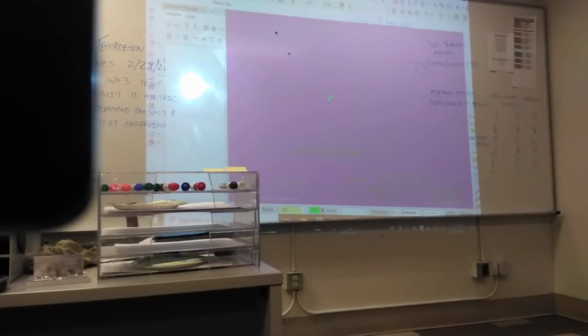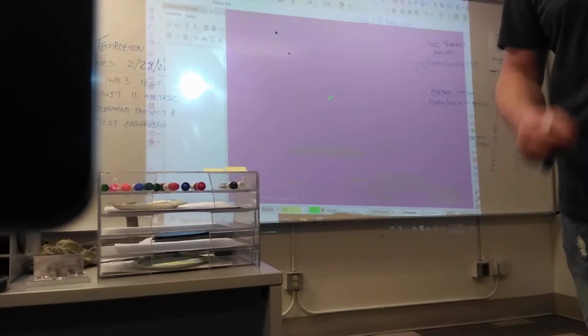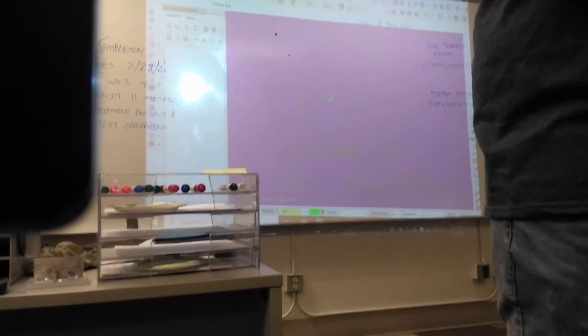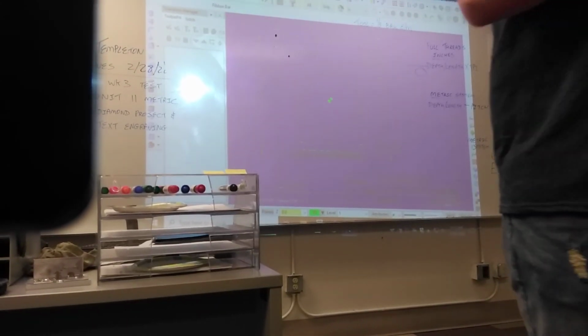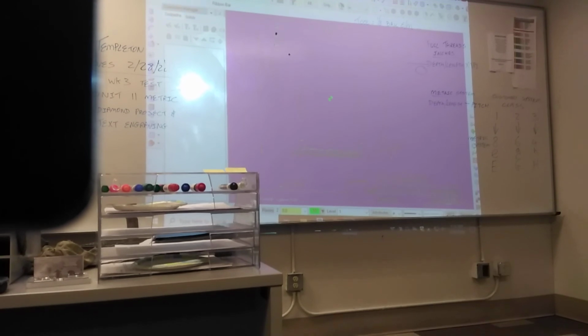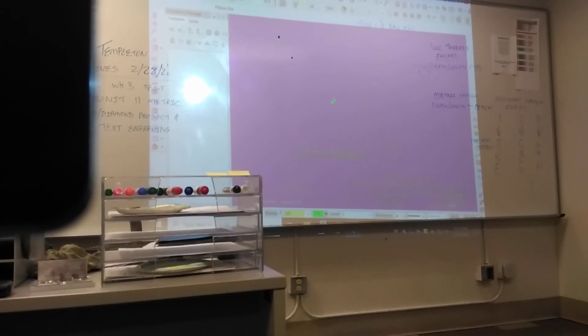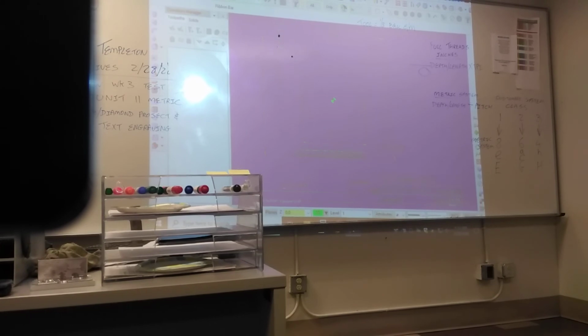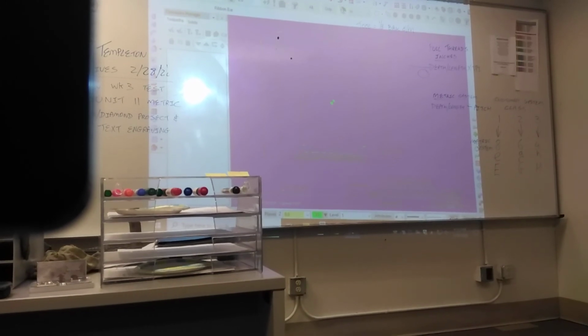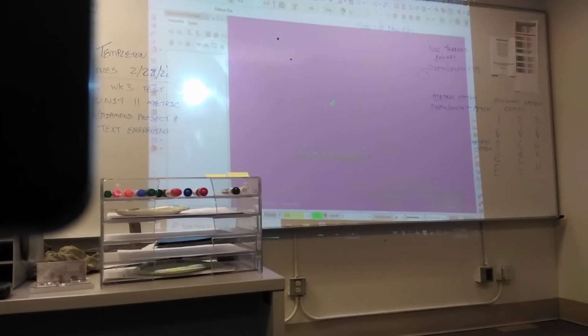What do we know about the material that you have? It's aluminum. What else? The dimensions. It's thin. 3 by 3, 1/4 inch. But what do you know about this surface here? It's unfinished. Is it flat? No. So if you try to engrave on the top, certain parts will be deeper than others because it's not flat. So what do we need to do before we engrave it? Finish it. We're going to fly cut across the top to make sure it's flat. Then when we do the engraving, it'll be the same depth all the way around.